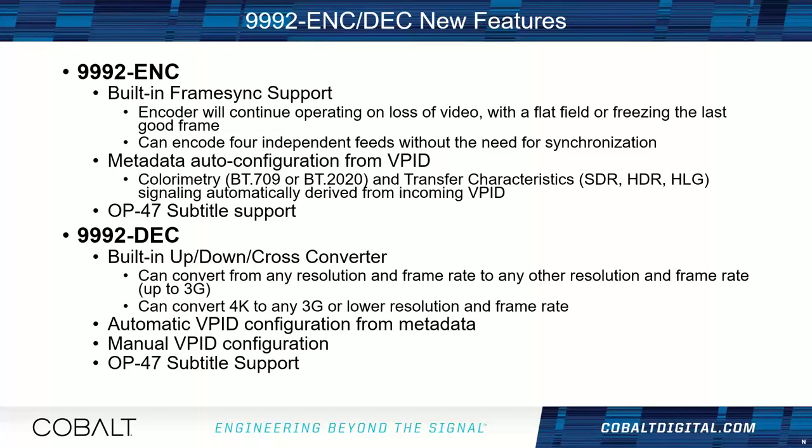Same thing, automatic VPID configuration for metadata. So it's going to read the metadata and put the VPID out for you. We can also override that and do manual VPID configuration. And since we did OP47 in the encoder, we also did OP47 in the decoder.